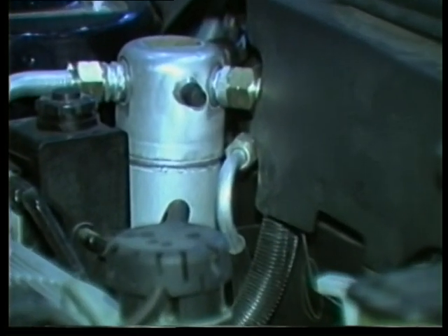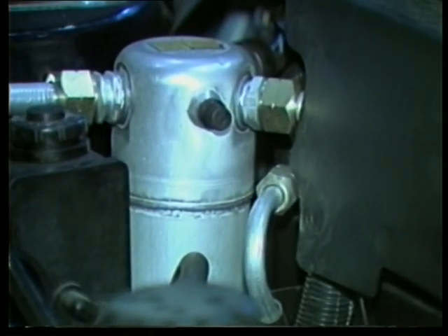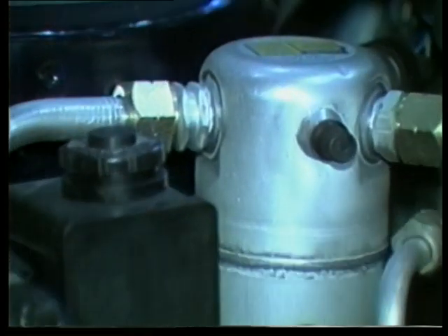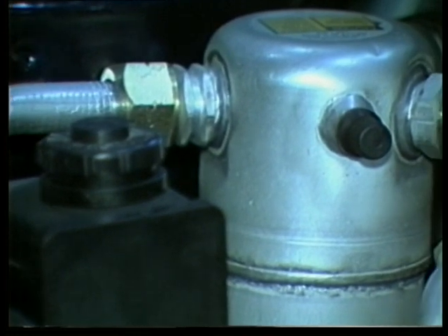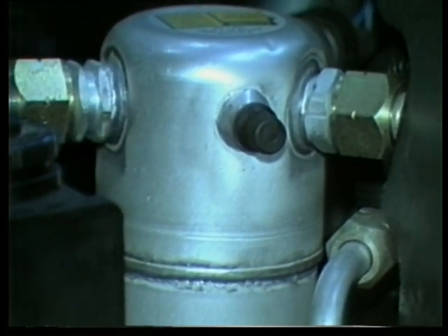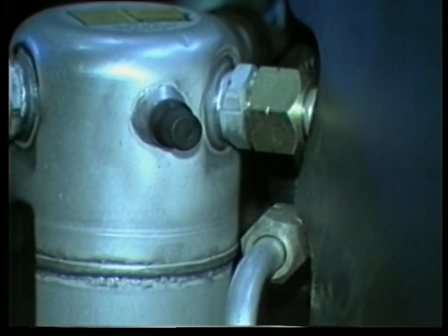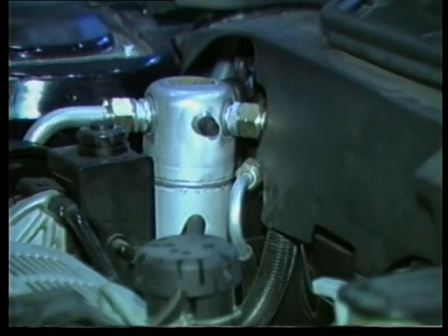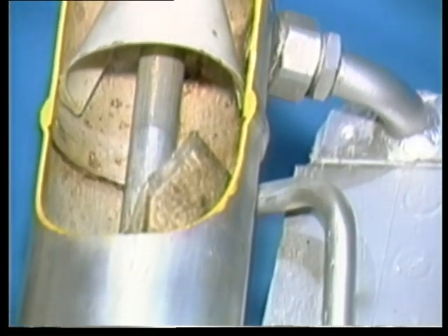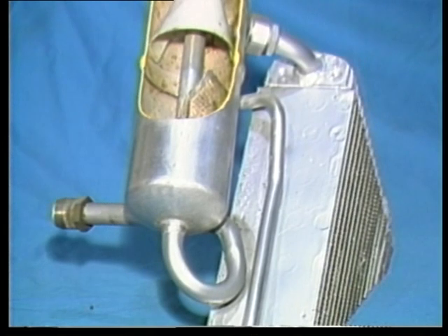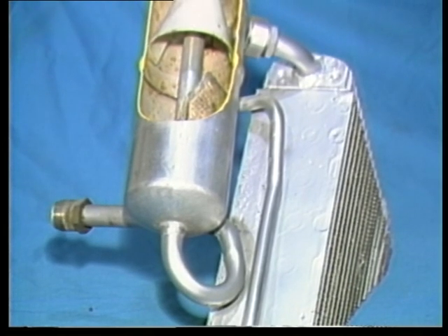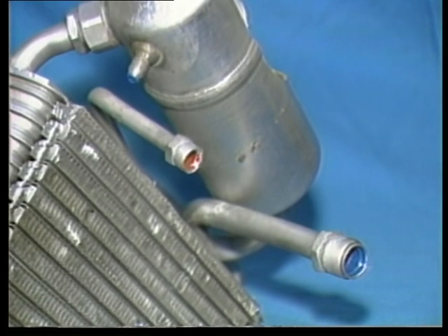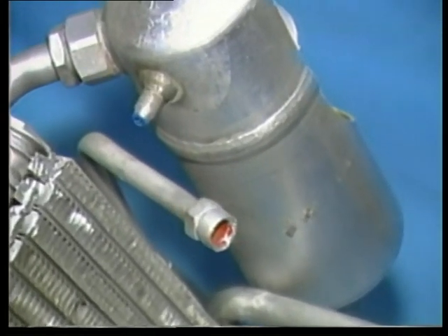Any liquid refrigerant settles to the bottom of the housing. The vaporized refrigerant floats out the top and is pulled back into the compressor inlet. Liquid R12 vaporizes as it warms inside the accumulator. Note the desiccant bag, which absorbs moisture. A service fitting is often provided on the accumulator for connecting your low pressure gauge for testing system operation.